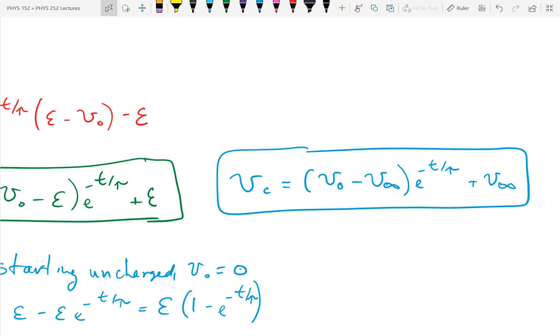You have to combine them using our rules for series and parallel resistors. What if instead of one resistor, you have one problem that has two resistors in series, or capacitors? You have two capacitors in series. What do you do if you have two capacitors in series? You're going to have to combine those. That's correct. So you'll just treat them as one, but you have to combine them to get the new capacitance. Yes, that's right.